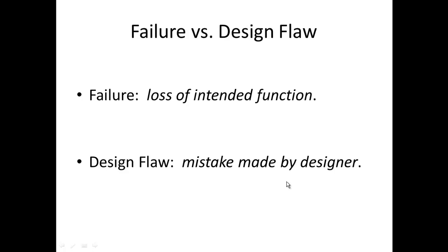And for the Cadillac engine, the material incompatibility there is a clear design flaw. There's just no way that the cast iron and the aluminum should have been coupled together in that geometry. Had the engine been made all of aluminum, then it would have expanded and contracted in a reasonable way, and that design flaw would have been averted.